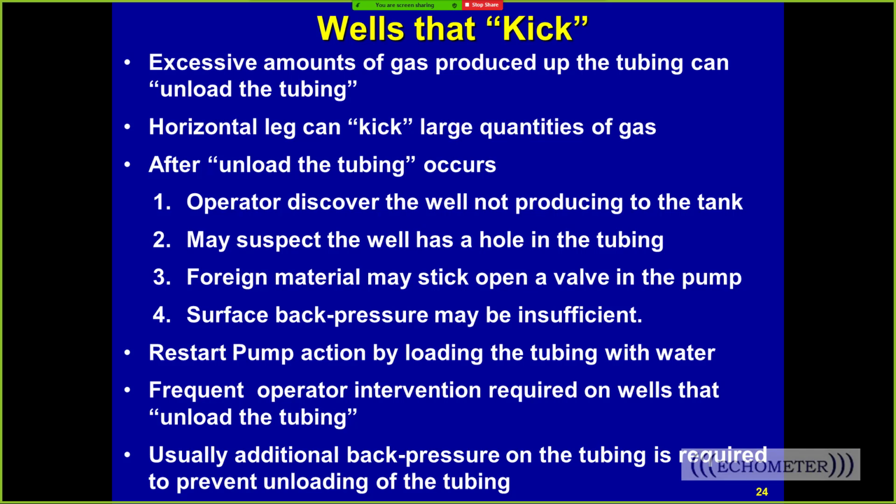All right, now John was dealing with quite a few wells that were new, and it wasn't uncommon for him to go to a well that wasn't producing any liquid, the rod pump that was turned off, because the well had poor gas separation, and they were pumping lots of gas up the tubing, and then the tubing gradient would get light, and the tubing liquid would flow off, and then the pressure differential across the pump would equalize, and the sucker rod pump wouldn't pump. And so we call that a well that had kicked, or the horizontal had kicked and blown the liquid out of the tubing.